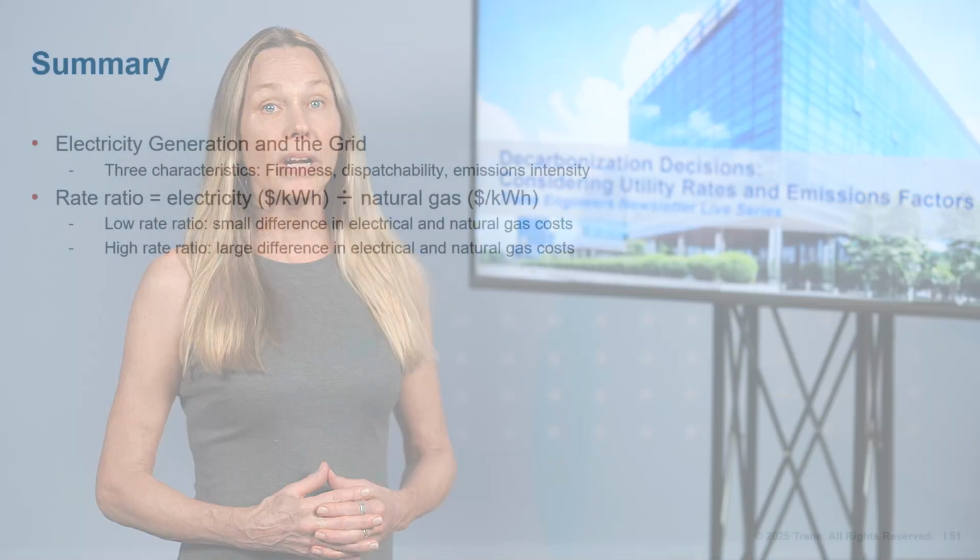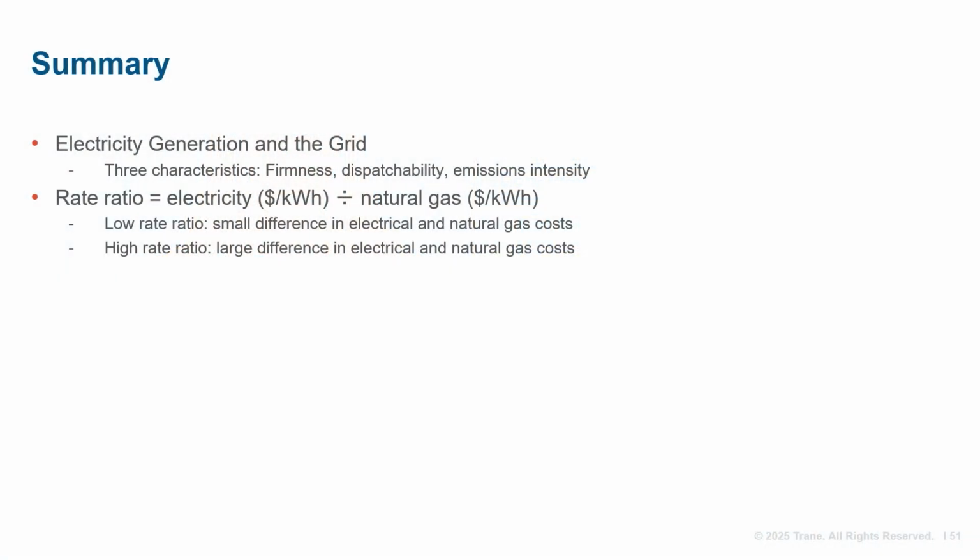Michelle discussed the rate ratio, the ratio between the cost of electricity and natural gas. A low rate ratio indicates a small difference in the cost of electricity and natural gas, whereas a high rate ratio indicates a large difference, often meaning the cost of the electricity is high compared to natural gas. The rate ratio can be used to help make preliminary electrification decisions.